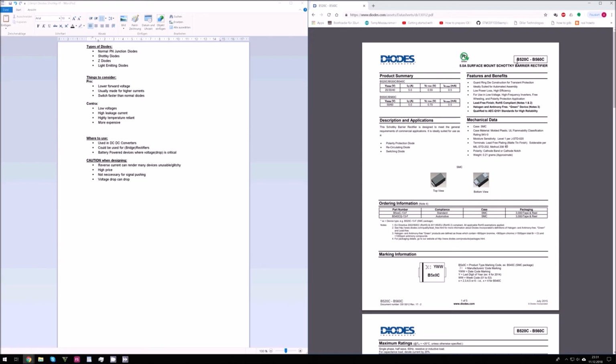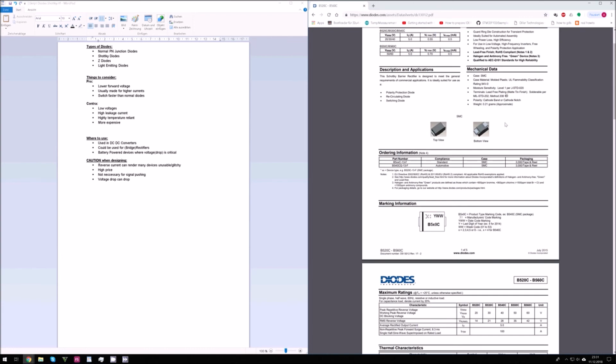The naming scheme is as follows. First, there is some kind of model prefix, and in the end, there's also some kind of suffix. These things usually you don't have to take into account. What you have to take into account are the numbers in between, the numeric value. The first number tells you the amperage. If it's 1, the diode can withstand 1 ampere. If it's 5, the diode can withstand 5 amperes. And here we're talking about continuous currents, but only under certain situations and conditions.